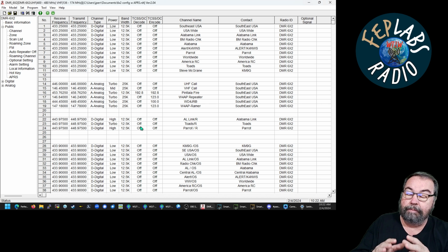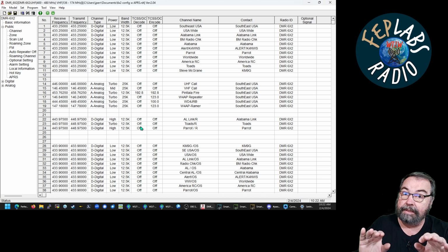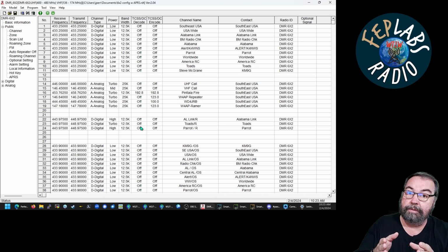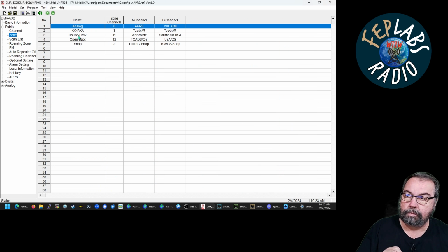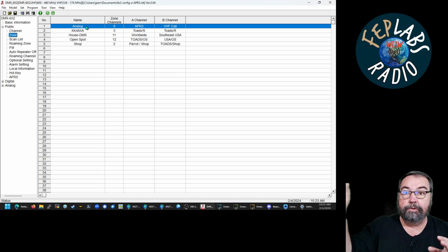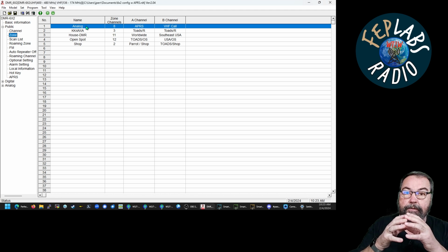Now, the next step, it's also optional. This is completely optional, but I highly recommend you do this because otherwise it'll make you crazy. And then you'll wake up one night and go, man, I should have listened to Jim when he said this. You want to do what's called zones, and that is our next step. If you come up here to zone, you can see I have 5 zones here. What a zone is, is a logical collection of all those channels that we've made, and they're lumped together in